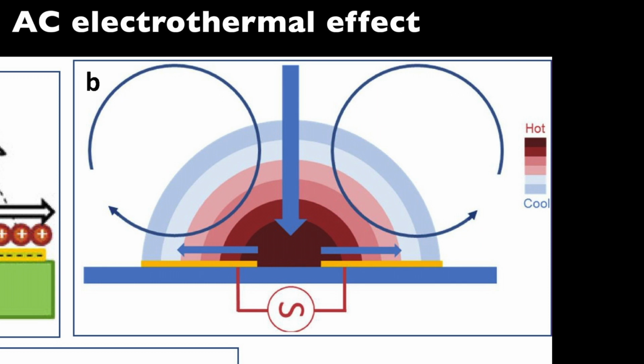So the resultant temperature gradient in the bulk of the liquid causes a permittivity gradient and a conductivity gradient, which in turn causes a net force called electrothermal force. In the bulk of the electrolyte, the time average electrothermal force can be calculated using angular frequency and the charge relaxation time. Unlike electroosmosis, electrothermal force is a body force acting on the bulk of the liquid, and therefore is not limited to the double layer. The electrothermal effect is thus a very useful tool for biological fluid manipulation.